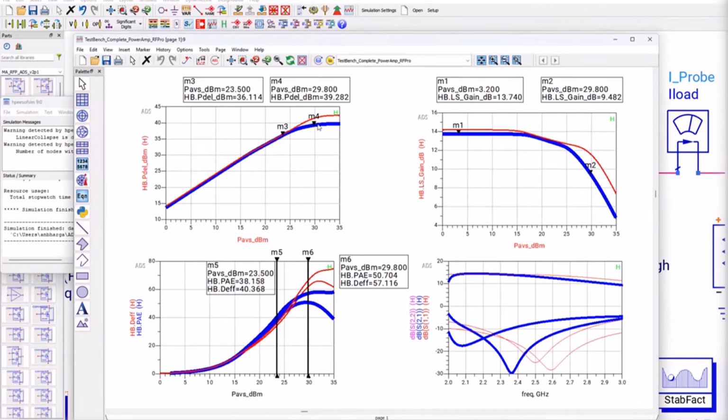See, towards the compression, now it is showing you lesser output power. And this is due to your impedance matching getting disturbed. So that's your problem with your core simulation, that slightly the way you did things, the match is getting disturbed, so your gain is getting dropped, especially more in compression. So your PA is compressing much faster than what you were hoping. And if you want, you can take some corrective action.